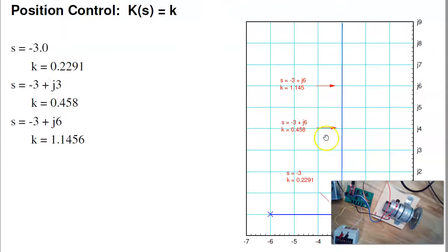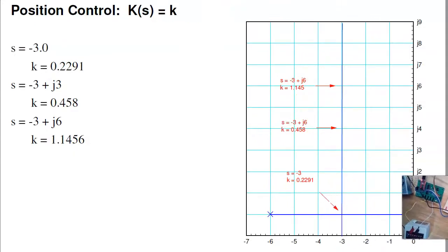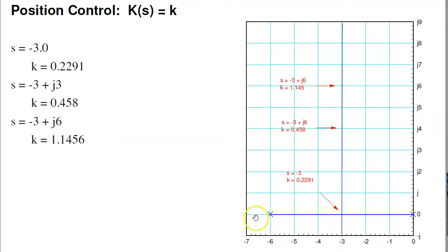I want to design a compensator for this system. So let's start out with just proportional feedback. If I have proportional feedback, what it predicts is I'll start with the pole at the origin, minus 6. These come together, split apart at minus 3. Depending upon the gain, I can get a slow system, a faster system with no overshoot, then I start getting overshoot. That's actually minus 3 plus j3, got an error there. Depending upon the gain, I can get whatever response I want.